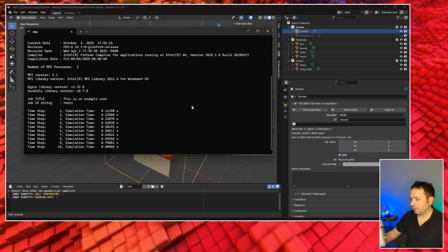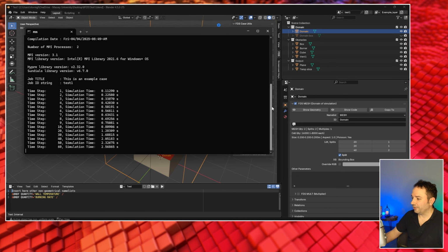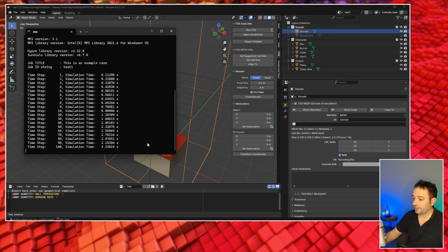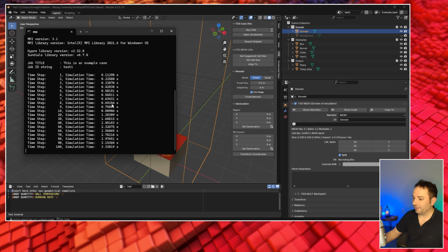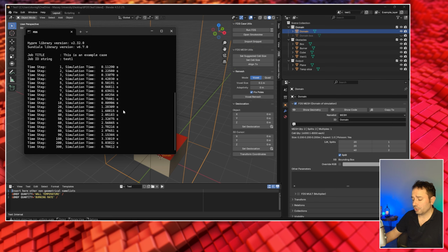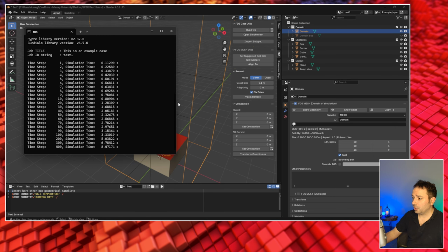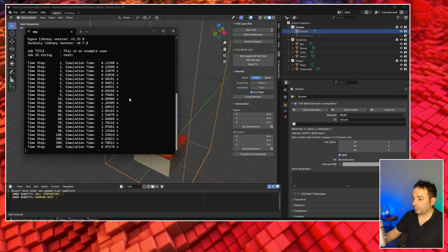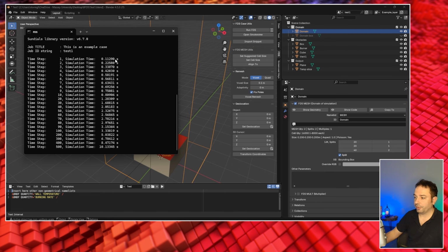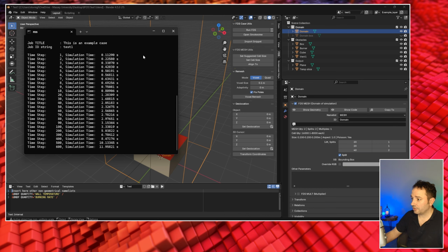But of course, you can't do this trick for a real simulation. You always need to have an accurate estimation of the cell size. This is just a demo, so we need something faster, so that's why we are doing this trick. And it will be good just to test whenever you have a new simulation and you want to just see if it's up and running and all the elements are working properly before you do the proper simulation. So we have already generated 10 seconds of simulation.